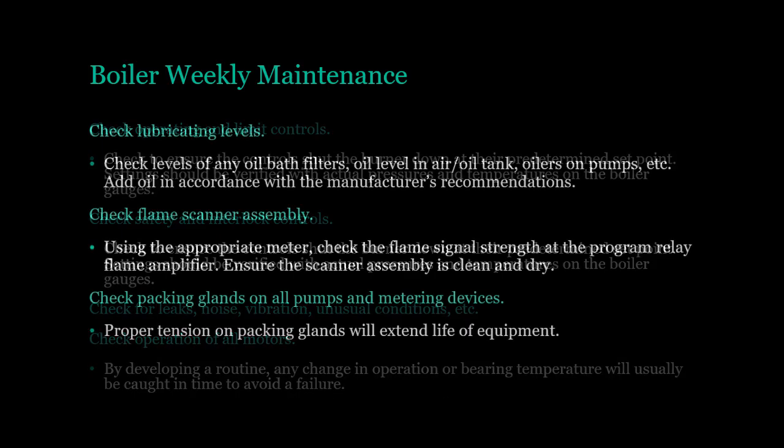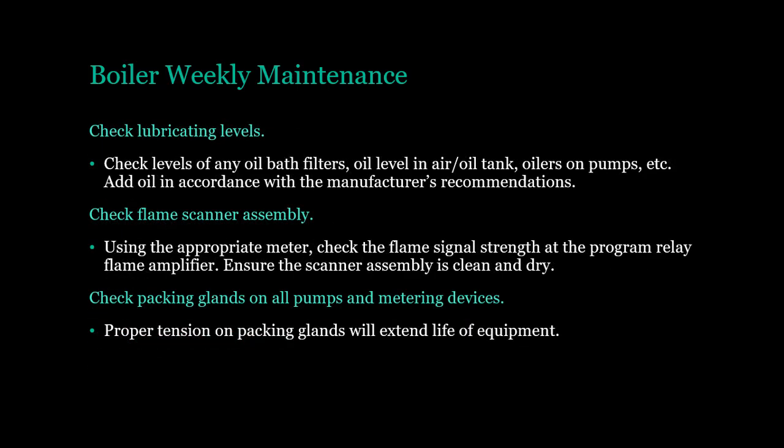Boiler weekly maintenance. Check lubricating levels. Check levels of any oil bath filters, oil level in air/oil tank, oilers on pumps, etc. Add oil in accordance with the manufacturer's recommendations.